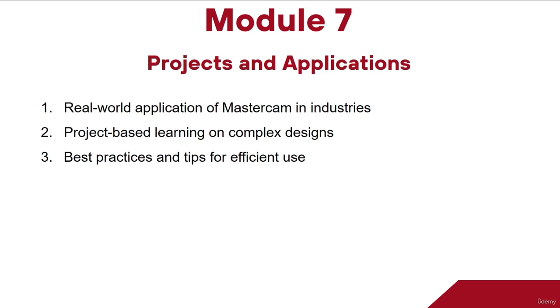After creating a 3D geometry, we apply 3D toolpaths on the 3D geometries. In the 3D toolpaths, we have two types: one for the roughing operation and one for the finishing operation. First we apply 3D roughing operations to the 3D models.